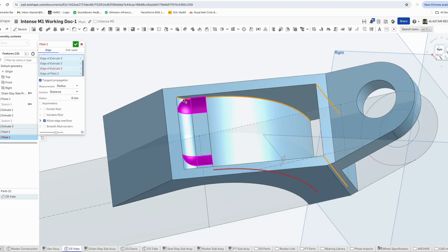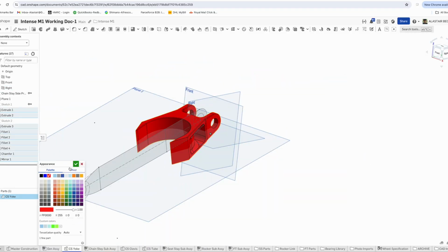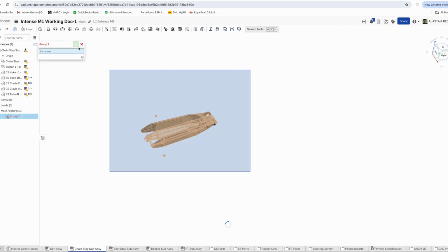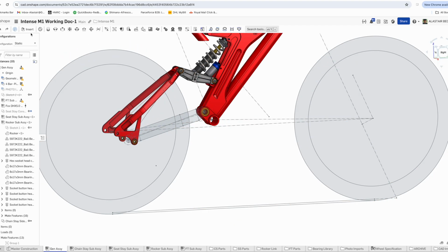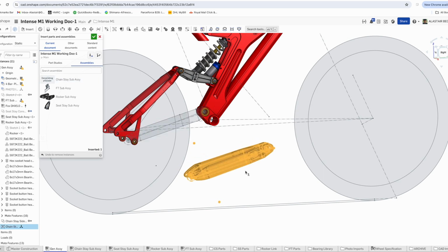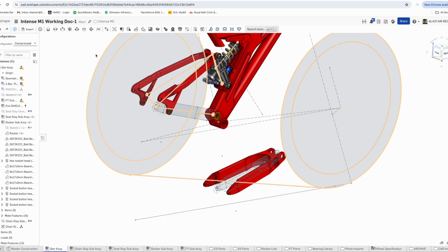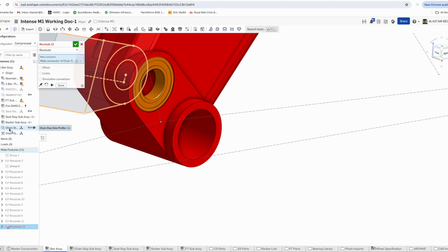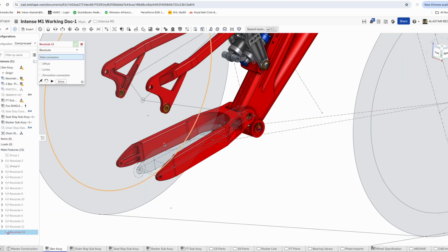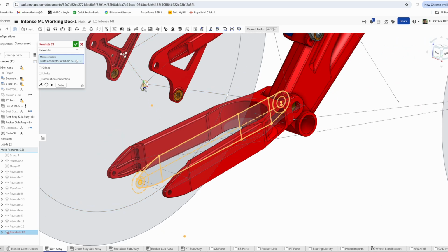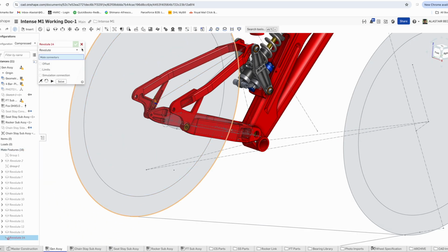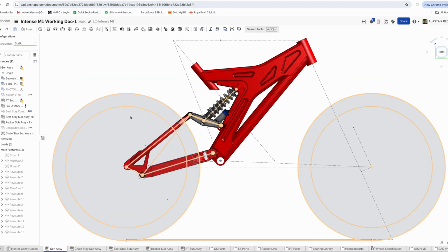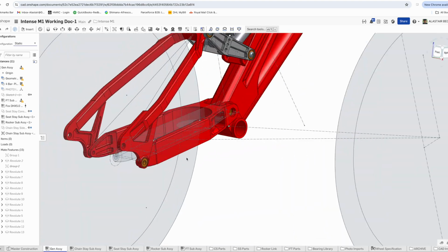And now going back and adding some of the details in the hollow pockets on the clevis just to try and match up. And we've got a finished chainstay assembly. So we're going to bring that into the main general assembly again, like we've done with everything else. Just check that those mates go in place. You'll see me flick between static and compressed in terms of the configuration for the full frame. I tend to mate stuff in the compressed setup just so that you don't end up mating to something that's maybe not correct. So it's good practice possibly to reduce those errors.